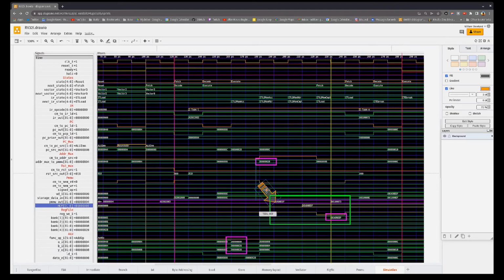So here it is. Now, one thing to notice in this green area that I have highlighted here is that when we're trying to load registers, we really need to hold the data, the setup time, and the hold time. The problem with trying to read it straight out of the MMU is that on the falling edge, we're moving into the fetch state, which means we're also going to wipe out the previous address, and it's now loading with this address, the next instruction, which is the break instruction. And we don't want to load any of our registers when data is changing like that.